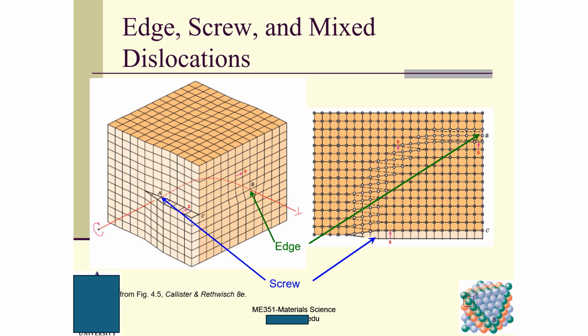So this is a screw, just a screw rotate. You just rotate. Just assume we have a center for this rotation, and just rotate it. And so this is the top portion and this lower portion, and they have relative motion. So this is mixed. You need to know that this is mixed. This is not just edge dislocation or screw dislocation, both.